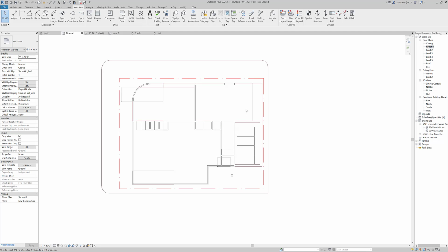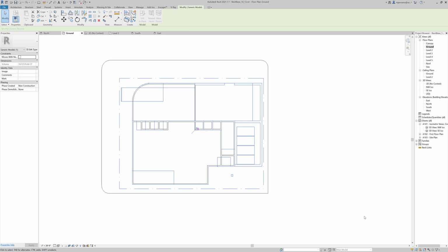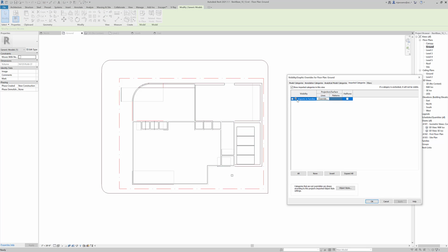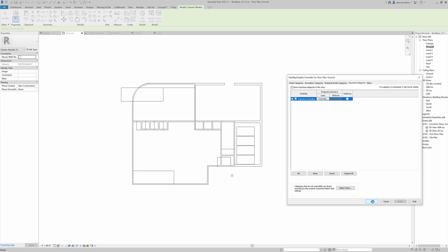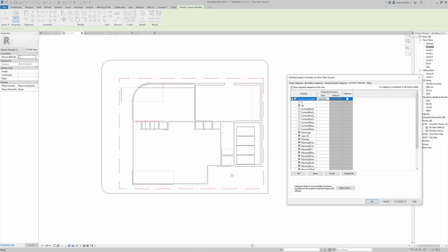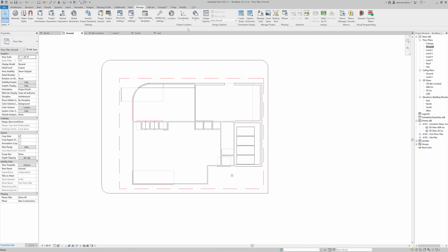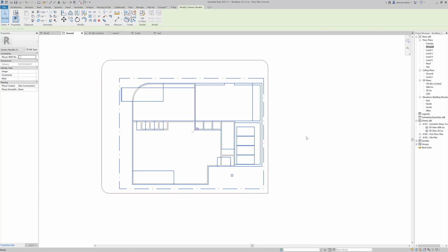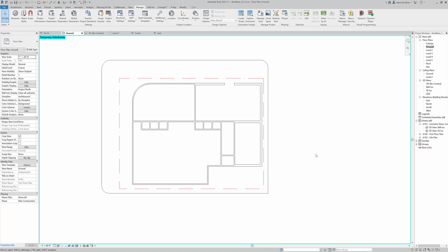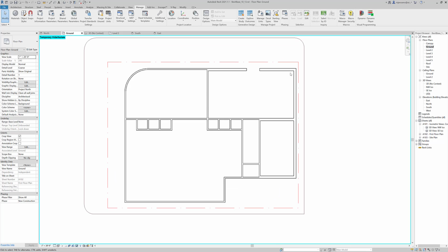I'm going to unpin my Rhino model, and I'm going to hide it temporarily. You can either turn that off by going to VV and turning off the import, or you can use the shortcut HH. Of course, there's more than one imported family here, so this is the benefit of having a linked file, an AutoCAD linked file. So actually what I'm going to do is select it and use HH as the hide in view, and you'll see this temporary hide isolate comes up. But that's fine. So what I have here is just a sort of foundational layer, right?